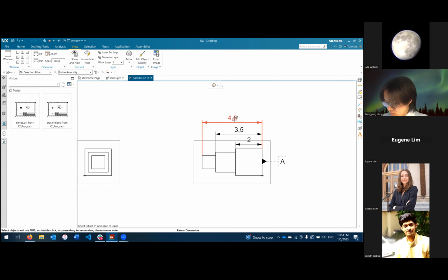And so while control features are great for putting a specific tolerance on any feature that you need and communicating that precisely, it is difficult and takes more time to manufacture something using that sort of precision, because it's more precise.